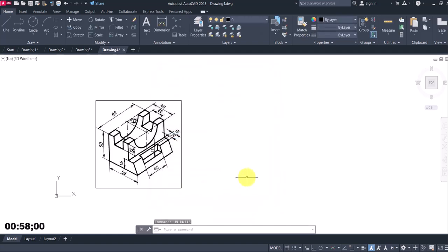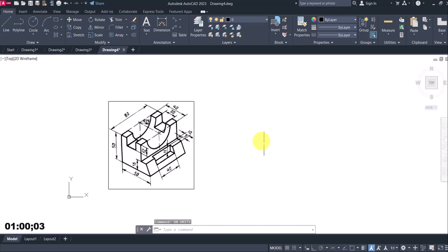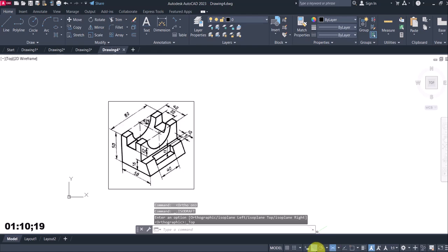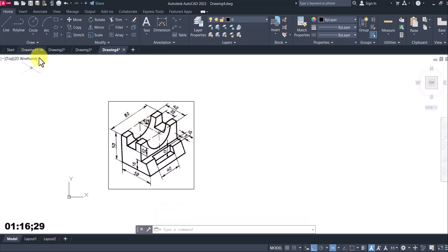Okay. Then next, I'm going to do the setting for isometric drawing. To do that, I will turn on Auto mode on my drawing aid. I will also turn on ISO draft. When you turn on both Auto mode and ISO draft, it makes your setting okay for isometric drawings. Then next, I can now start with my drawing.